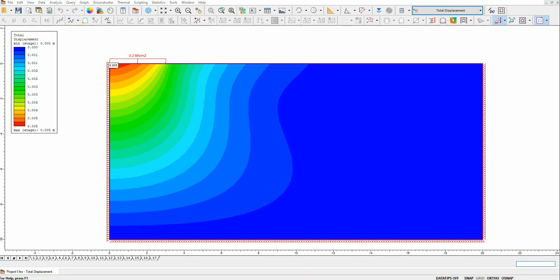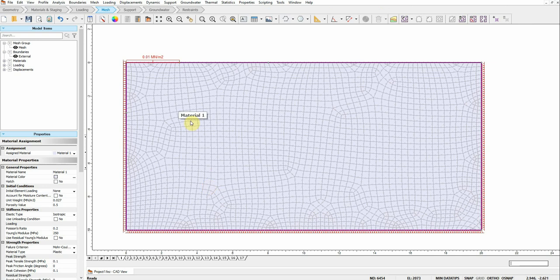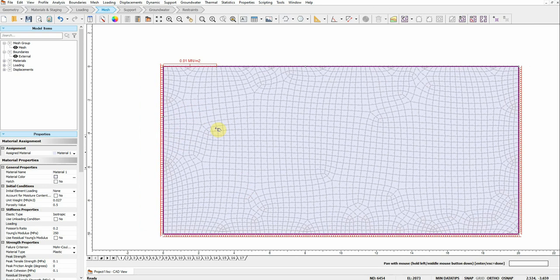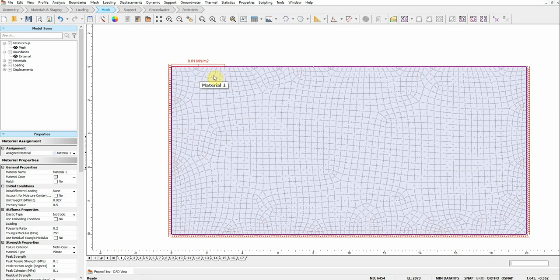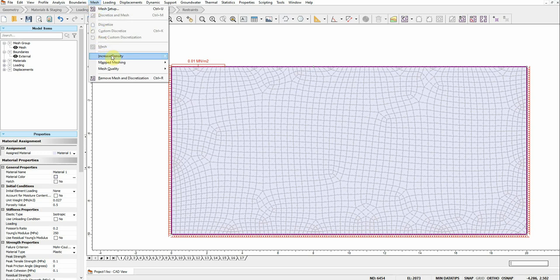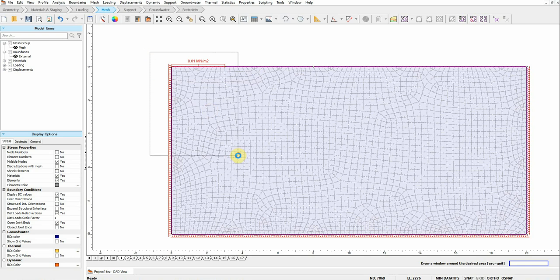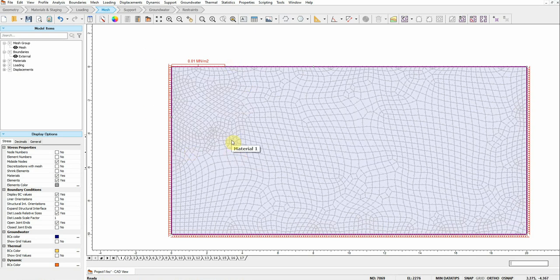And for example, if you have at this region, you have some sensitive soil layers or some sensitive information, and you want to make the mesh more fine, you can just go here and click on increase mesh element here, for example, and the software will automatically make the mesh finer wherever you want. For example, if you have many different thin layers here, you can make the mesh finer wherever you want in the model and make everywhere coarser.